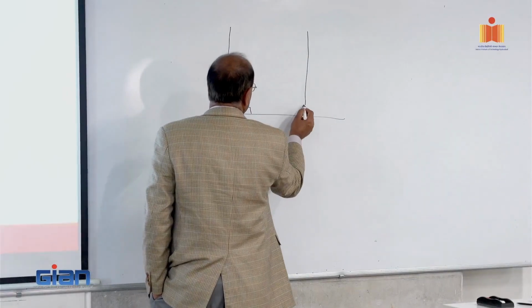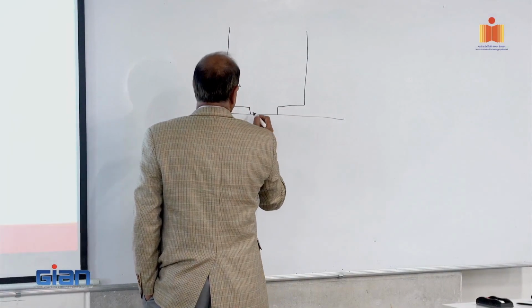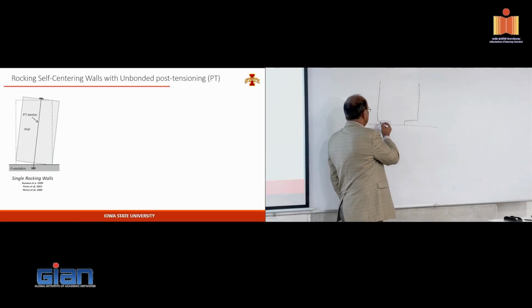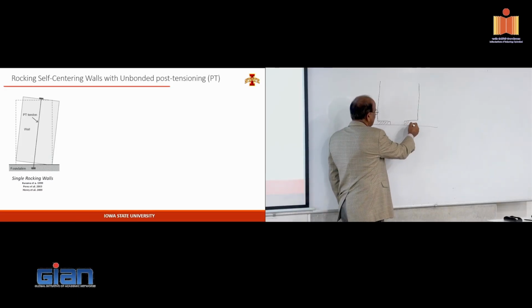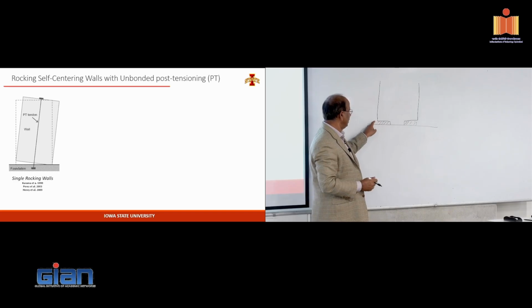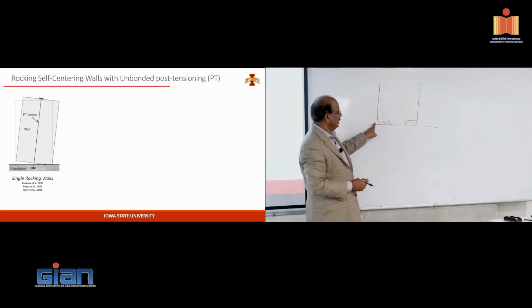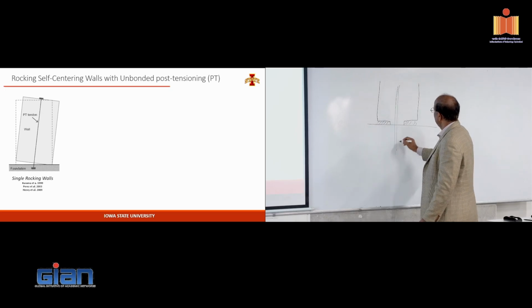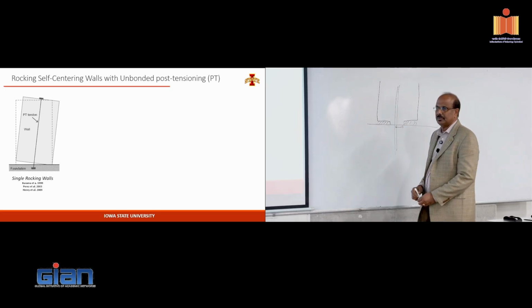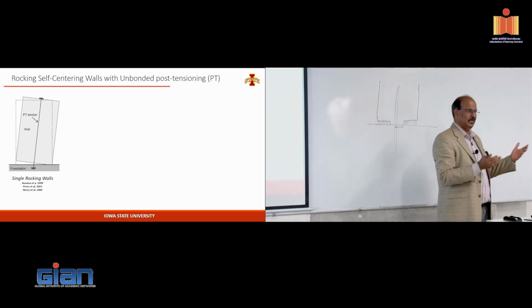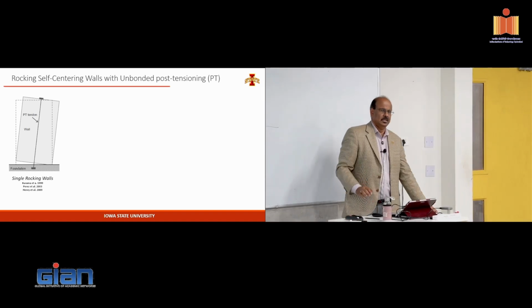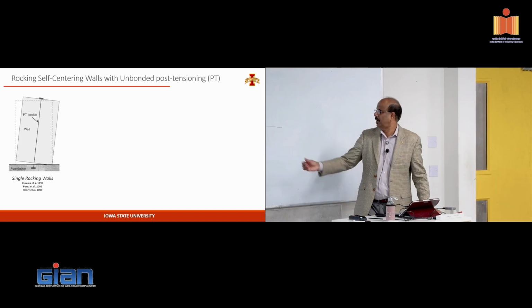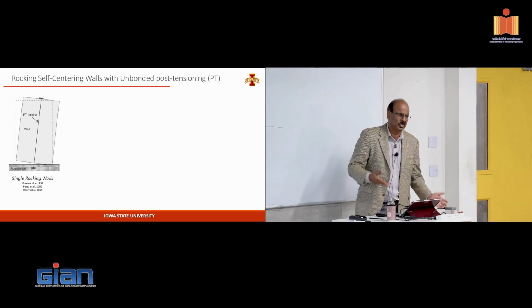If you want to cut down the amount of moment resistance but act as a pin, you could leave a gap here. Typically they will put in some deformable foam, and then run the cable, the reinforcement, in the middle, so the lever arm is now reduced. You could cut down the resistance by 90% or so roughly by adjusting your contact area.